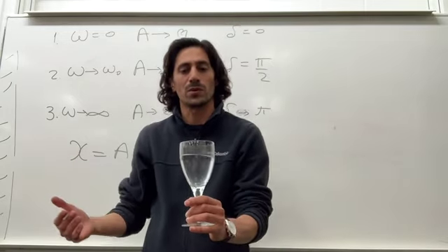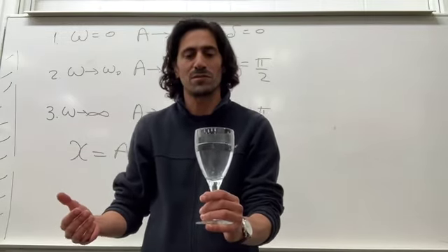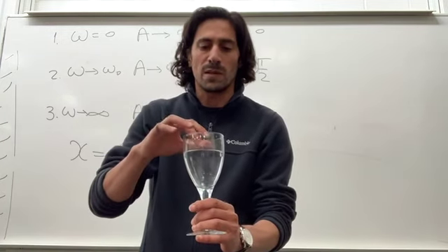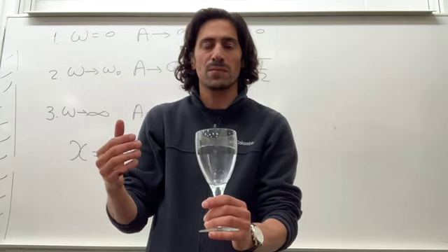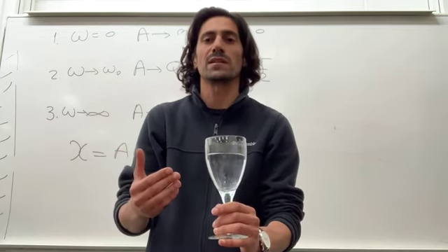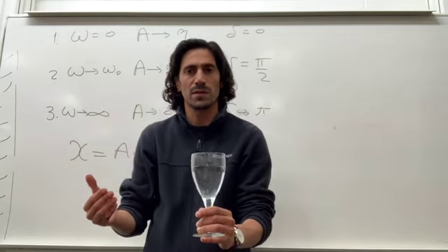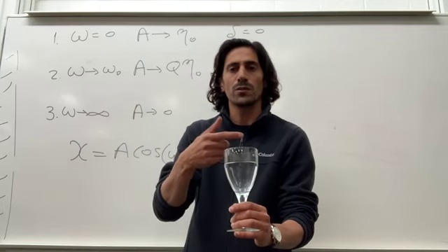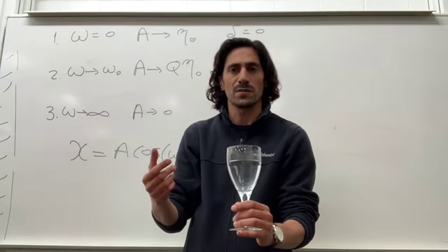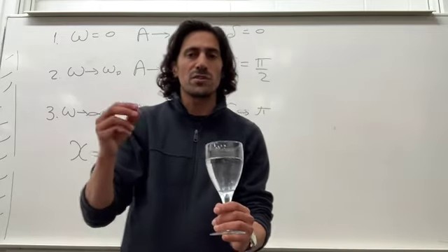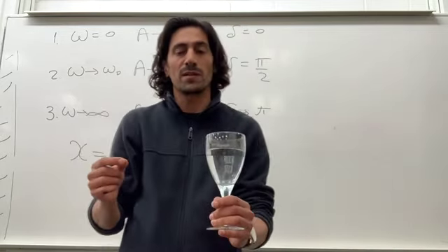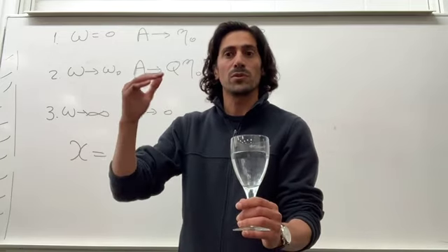We're going to get to this subject in depth. But one of these modes that you would be exciting would be the resonance frequency. As a result, the whole thing would start resonating at that resonance frequency. So what you would normally hear very gentle from other frequencies, suddenly the amplitude is amplified.